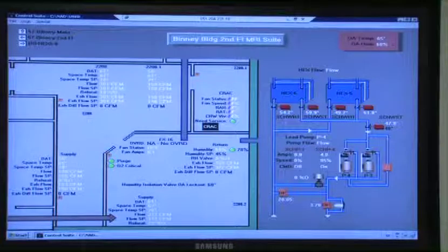The supply box is outside the room, correct? No boxes are inside the MRI room. I can tell you right now, only ductwork and diffusers are. Any boxes are outside this area. As far as representation, the thermostat for the MRI is on the door. It's actually on the other side of the wall, but just so there's no confusion, it's placed on the inside of the graphic.